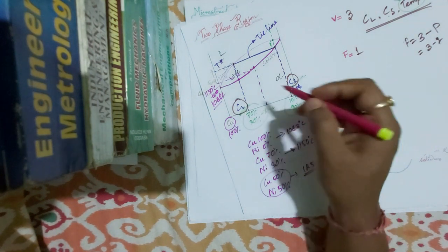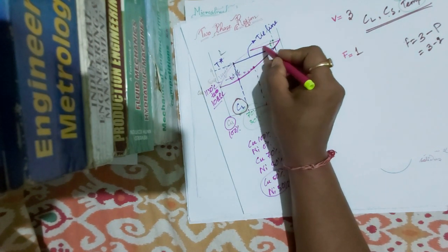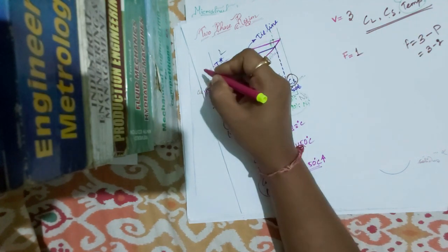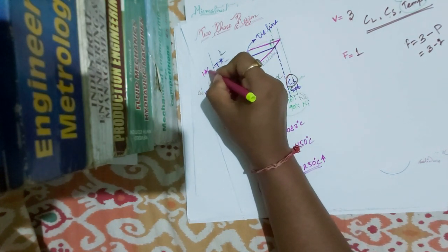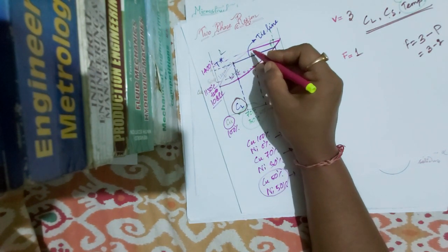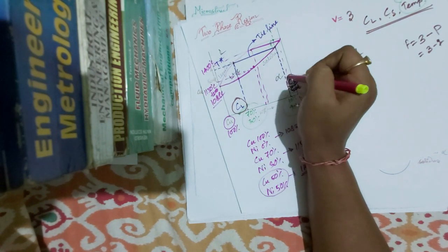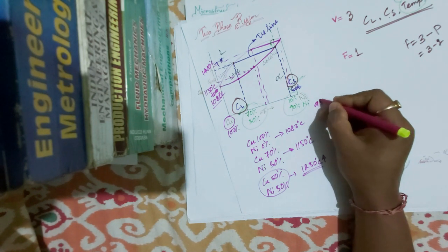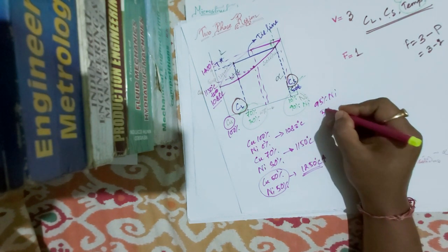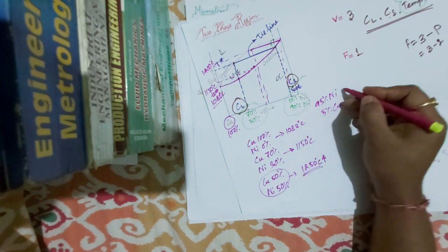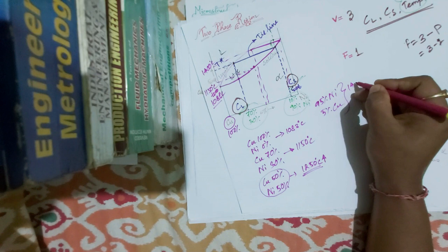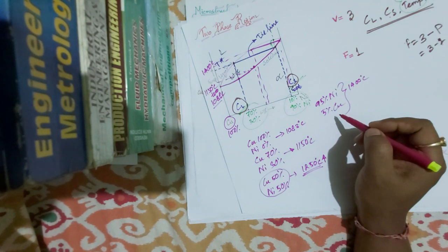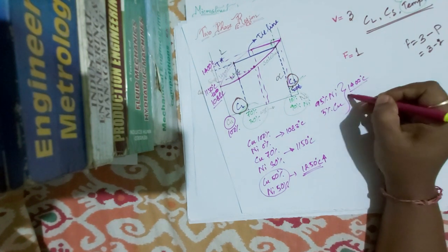So from here we can see, if we take this as tie line, and the temperature here is 1400 degrees C, the composition will change again. So let us say this composition consists of 95% of nickel and 5% of copper. So again the solidification temperature has changed, and now it is 1400 degrees C. So by varying the composition, we can change the solidification temperature of the component.